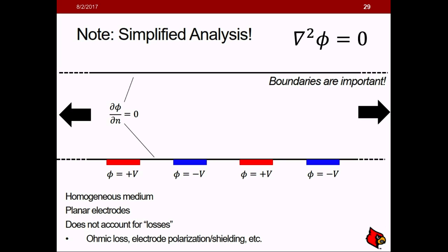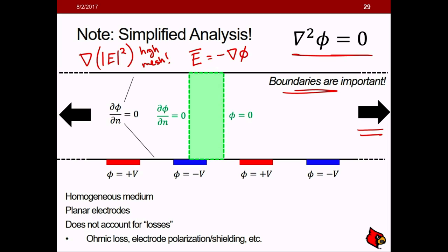So looking at this, there is a simplified way. If you were just looking at interdigitated electrodes, look for symmetry. One way is, say this is the middle of your device, you could cut it down the middle and simulate half of it, and that works. But think about what is the most simplified geometry that you could use for your system. For this example, this is what you would simulate.